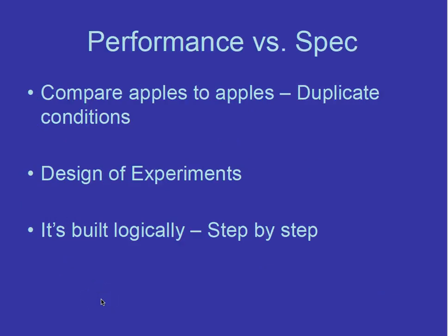So check that all inputs are appropriate to the block. Check the preceding and the succeeding blocks in the circuit. Sometimes there is signal present, but just because of that signal present between the previous and the next stage does not mean that the input is still correct. So look for those signs when you are troubleshooting.